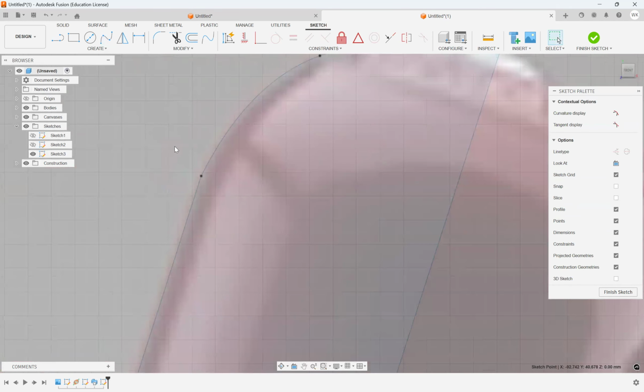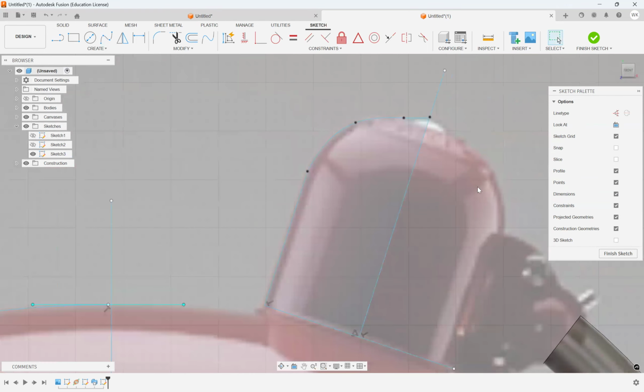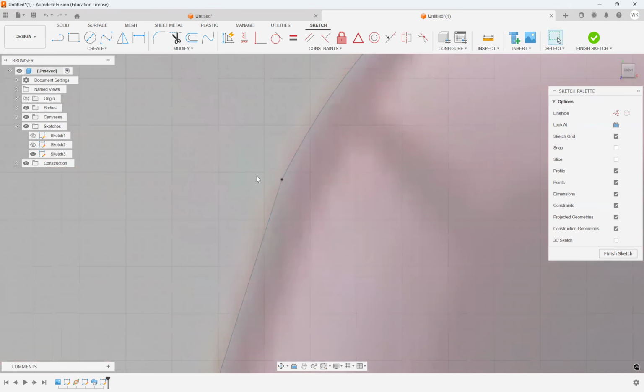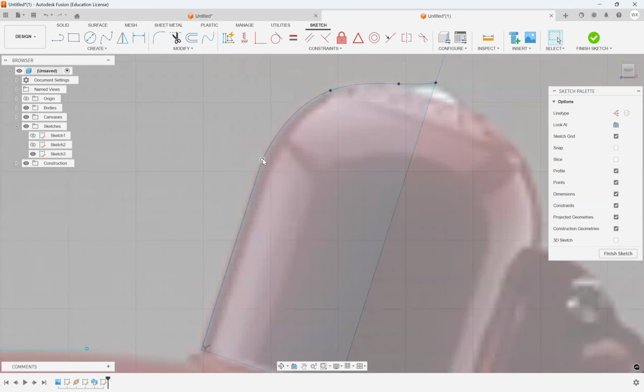And again, if you want it smooth, because as you can see, this follows very smooth lines in here, right? But right now it has very sharp edges. So to prevent that and smoothly connect these two, you use a tangent tool to connect these two lines in here, tangent with this end and this end.